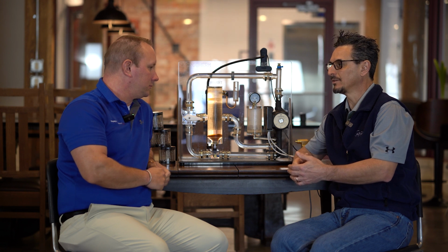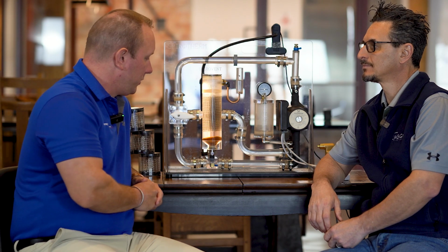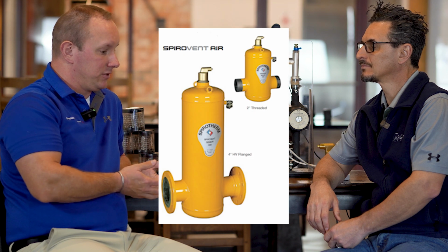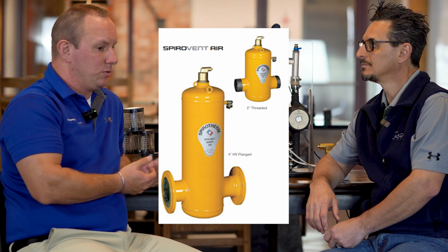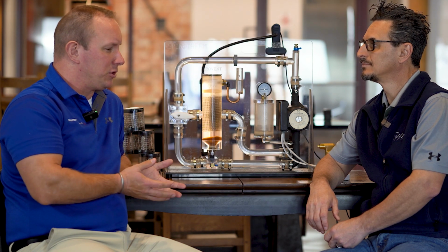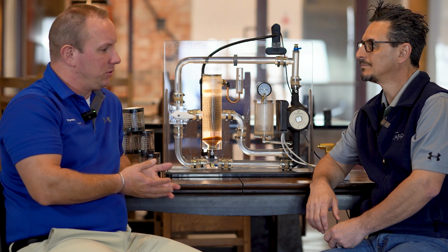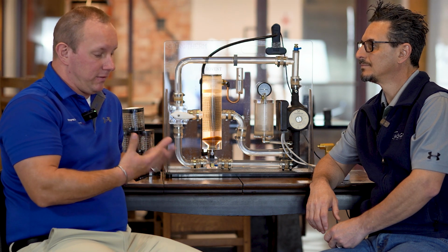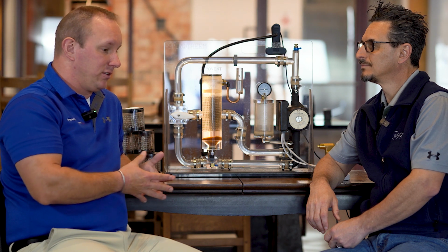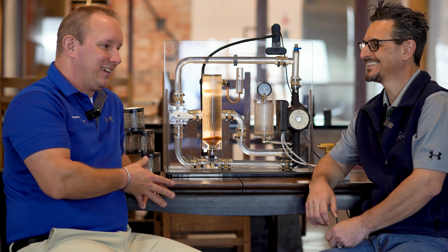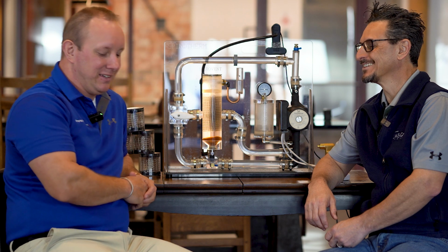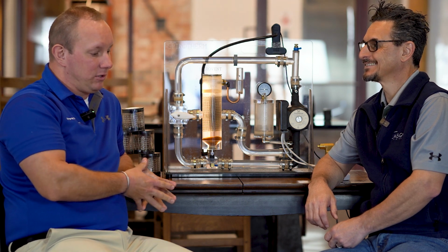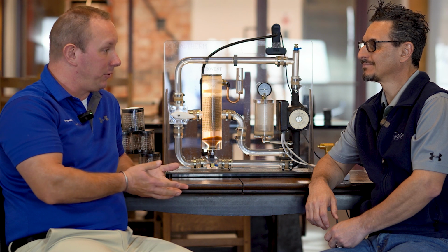Okay, so tell us about the 3 different types of Spirotherm products you typically see for air and dirt. Okay, so we do have an air-only product, which is kind of in its own name. It's an air-only separator. You can do that a lot in new construction, because we're not so much focused on the dirt in a new construction opportunity, unless there's something physically in the pipes. We've seen wrenches, 2x4s, face masks. I've heard underwear. Underwear is always a funny one. Yeah. So obviously with an air-only unit, we're only focused on the air part of it. So that's all that we want to get out of it.